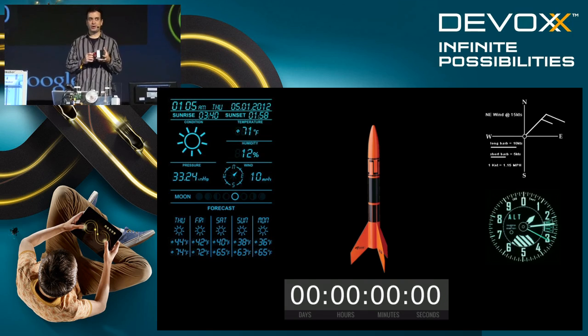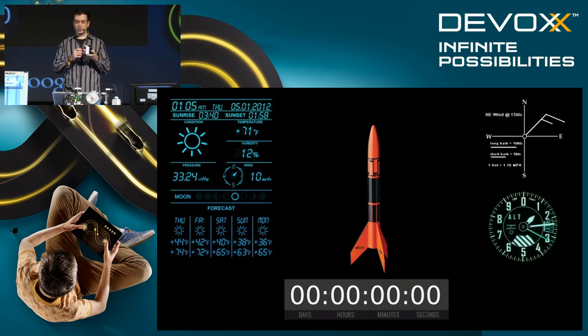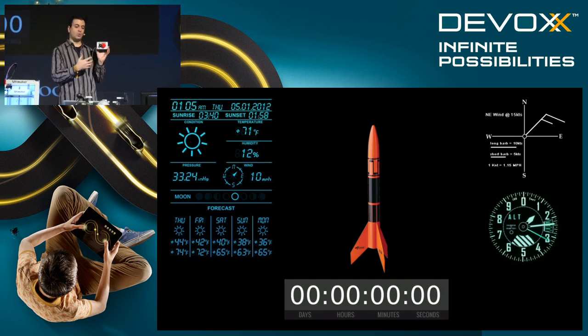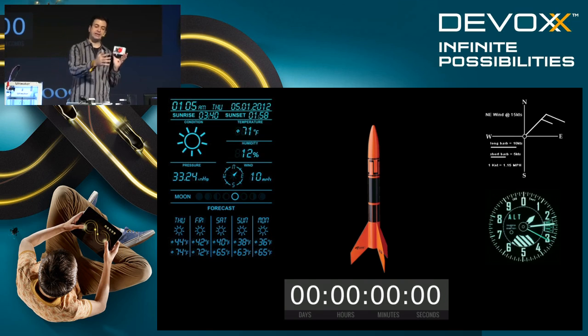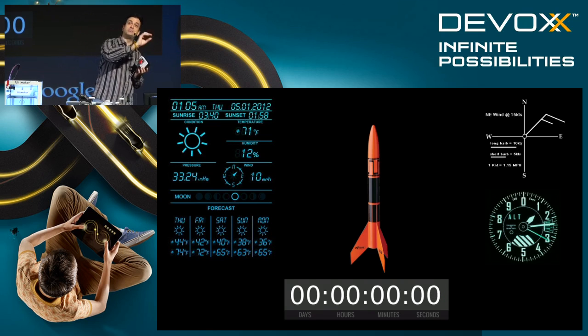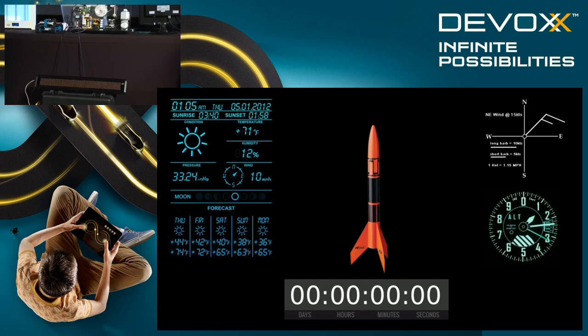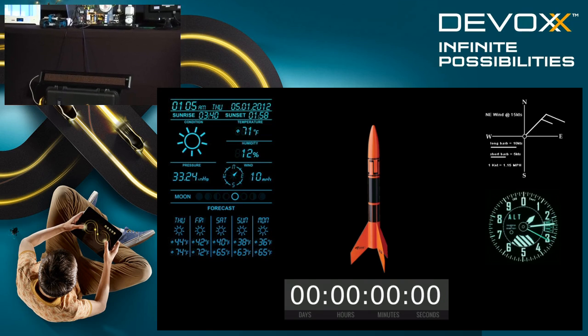Number 2, we want to test our abort functions. So when I turn the key switch, the safety switch, we're going to make the launch ready. What I expect to happen is that we're going to get an audible cue, a visual cue, a message on the message reader, and we're going to post the time on the countdown on the dashboard. And then when we abort out of that, by turning the key switch off or manually pressing the abort button, it should revert back to where we're at now.